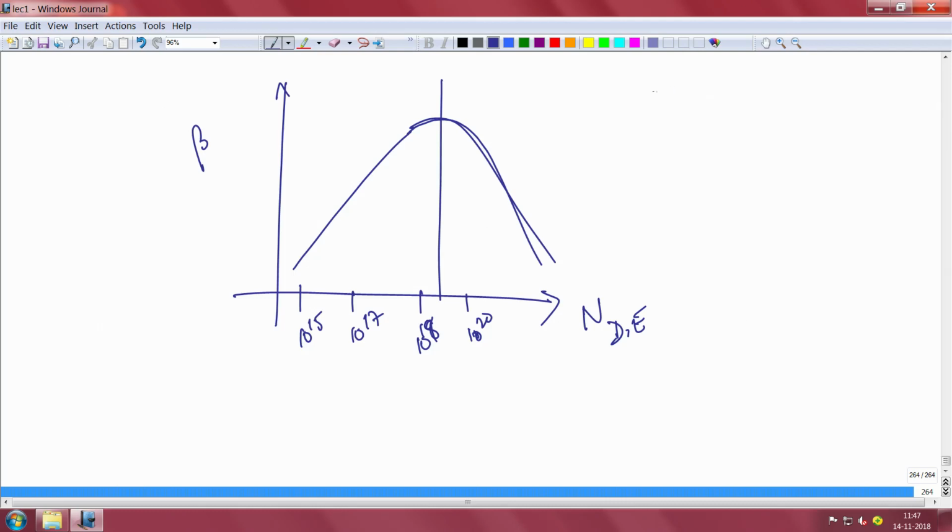So these are the things that we have studied. What we have studied? We have studied the various current equations, and the current transport in a BJT: the base component of the current, emitter injected current, base inducted current, recombination current, and so on. We have studied the base transport factor, the emitter injection efficiency, the beta, the gain, the current transfer ratio, alpha, these things.